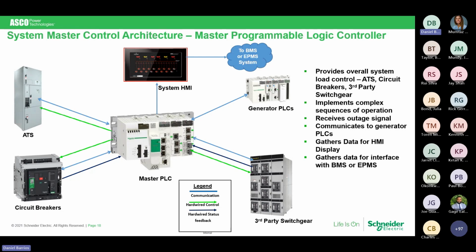You didn't show it. Well, why am I requiring that? If I'm on the ATS, it's coming down to where the paralleling switchgear is. I may need to convert my signals from Ethernet to fiber, run those down to the area, and then convert it back to Ethernet so that I can communicate with it.